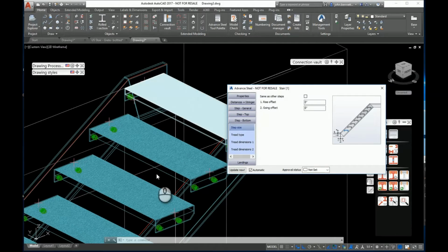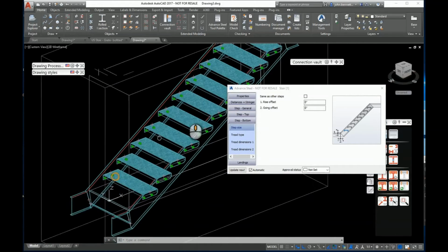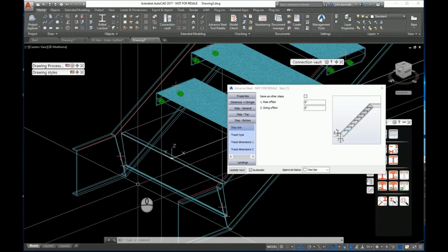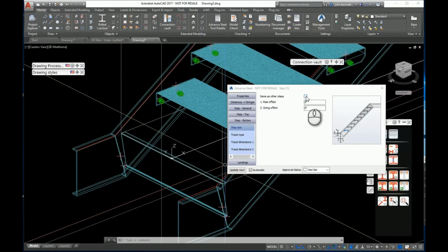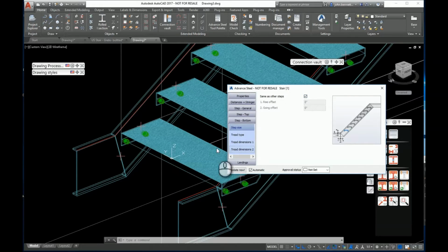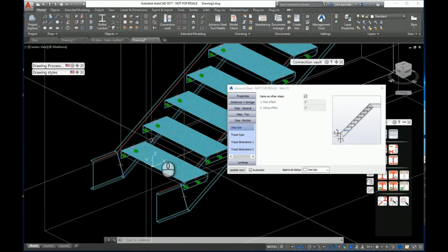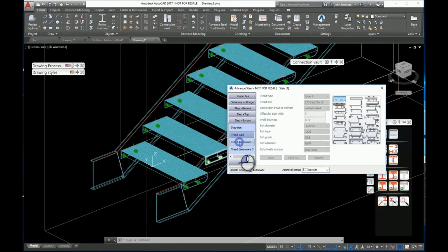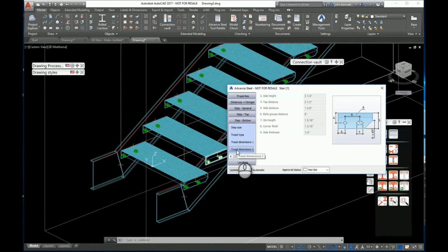So we're going to do the same with the bottom tread. You'll notice that that's not ticked at the moment, and it has a different infill panel that would have applied to the previous type of stair. So in this case we can check that box, and now it will make it appear the same as everything else. Again, the other fields or other tabs would be greyed.